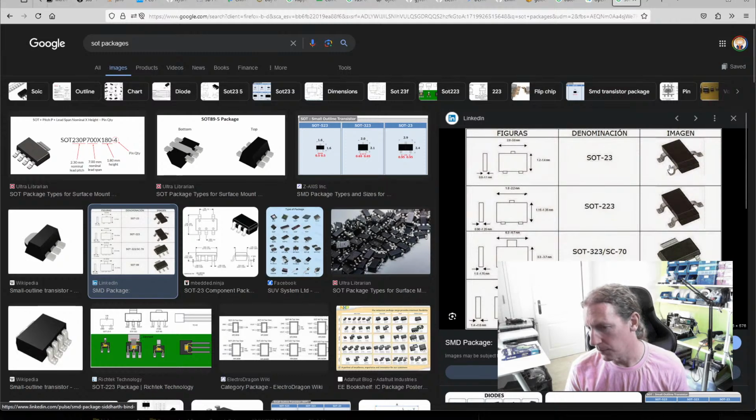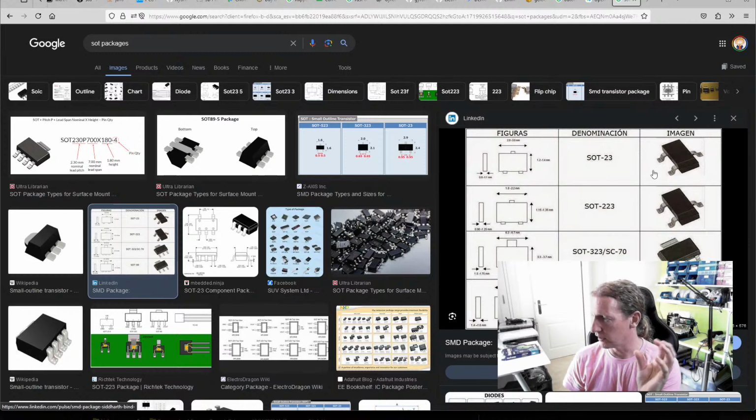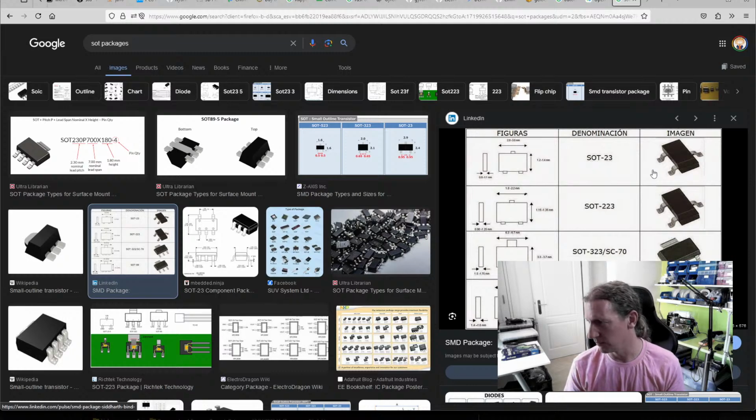and you pick up this part, you want to know that you've picked it up and which way around it's orientated. And to know which way that is orientated, you need to look at the shiny pads on the bottom of the part and draw a triangle over it. And then once you've got a triangle, you can have a vector to know the rotation of that part.